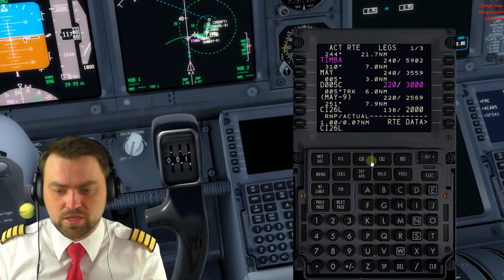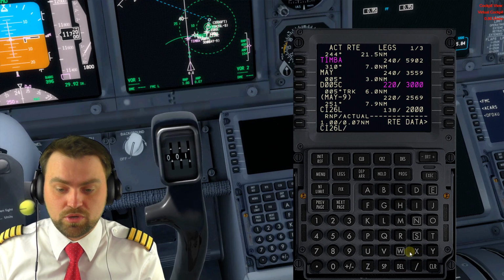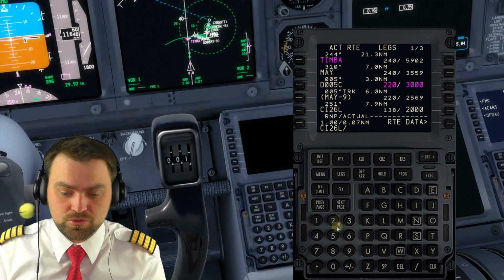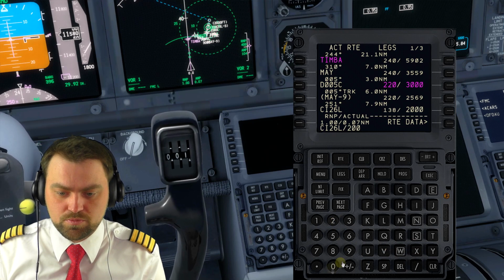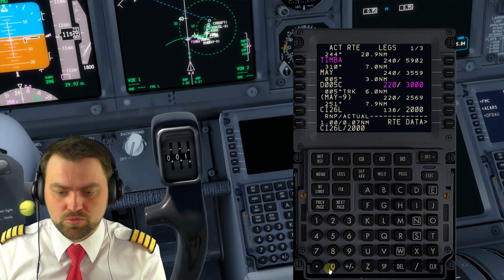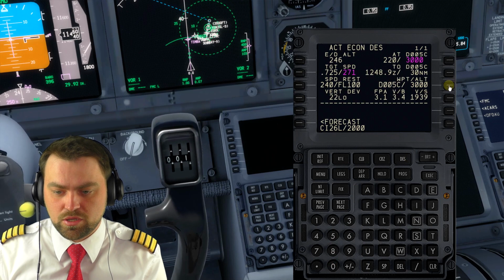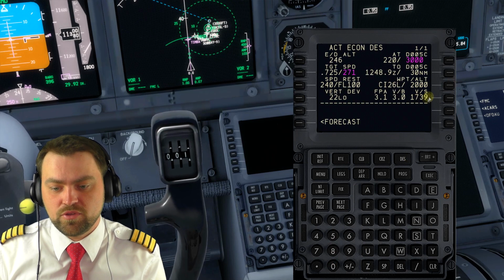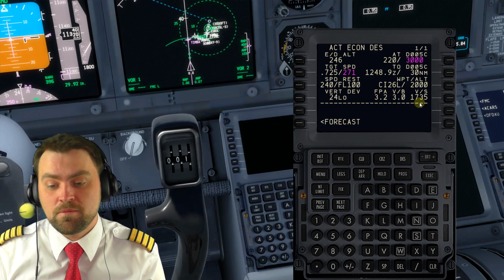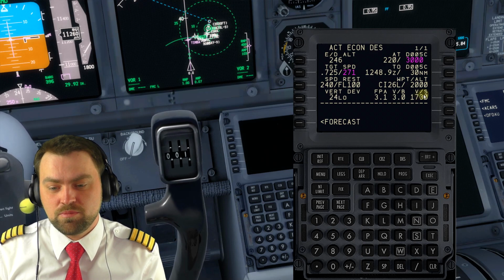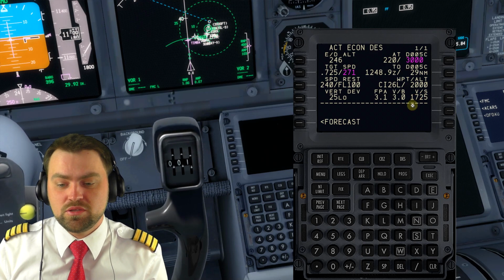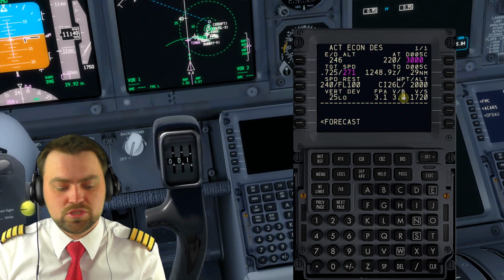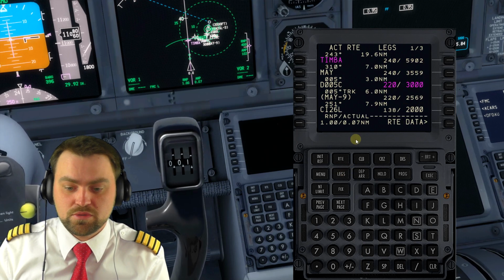And press it inactive. But what vertical speed should you require, because you shortened your route? So I put this point and altitude, what I need on that point, I put it here, and here I have the exact vertical speed for descent. But you should keep a little bit more, because it does not calculate your deceleration, because we are at 270 knots.